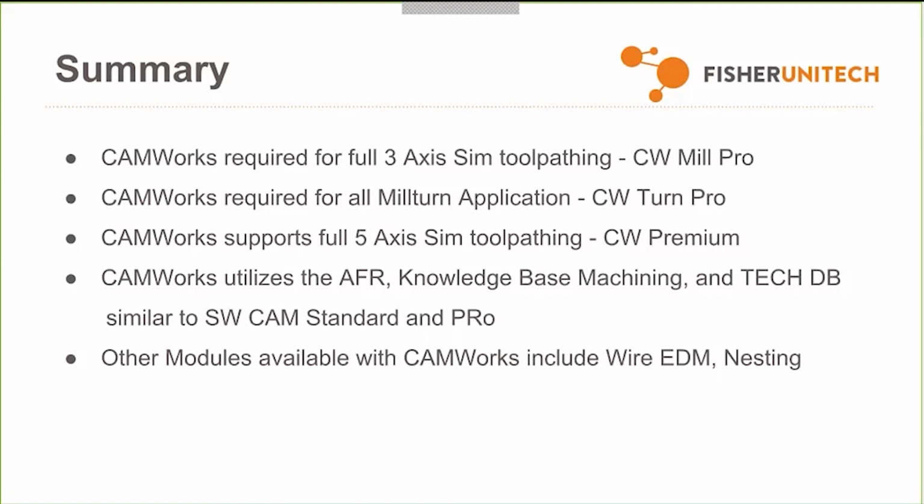It's also important to remember that CAMWorks utilizes automatic feature recognition, knowledge-based machining, and tech database, very similar to SOLIDWORKS CAM Standard and CAM Pro. Major differences with multi-surface features, a lot of times we have to go in and generate those features. They're not definable features, so automatic feature recognition will not recognize them.